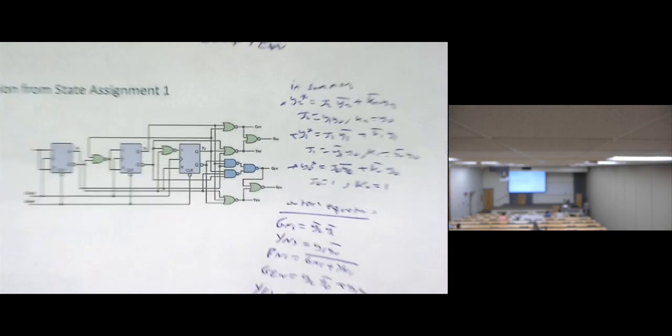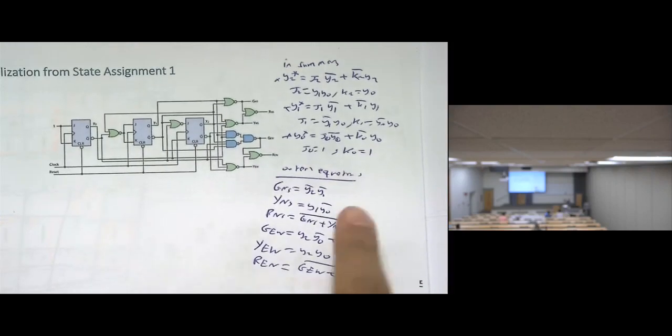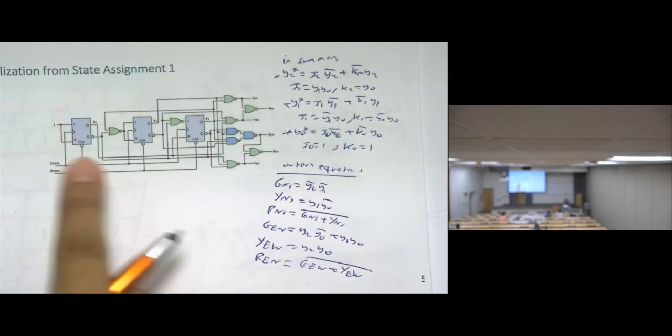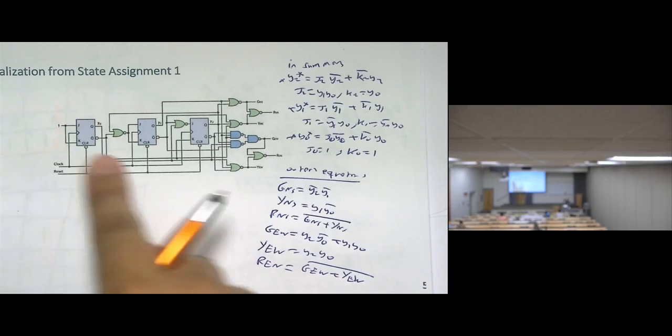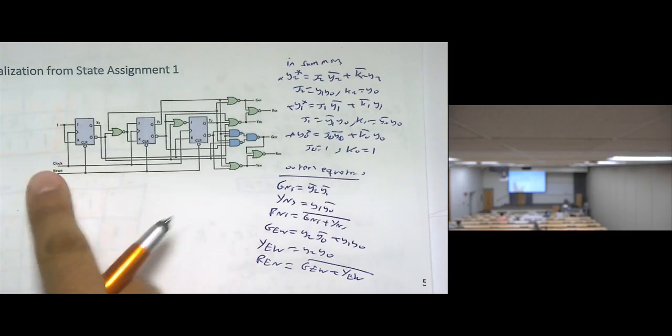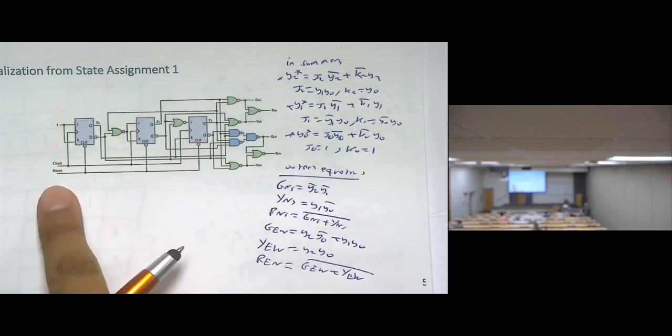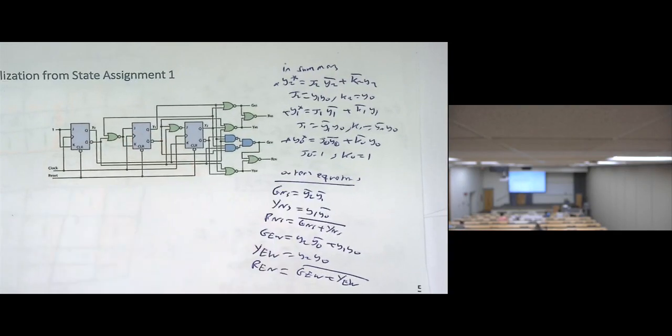Then with these equations, we make the plots to make this circuit. So we can build this design, connect the clocks, connect the resets, make the JK flip-flops default to rising edge, and that's it.